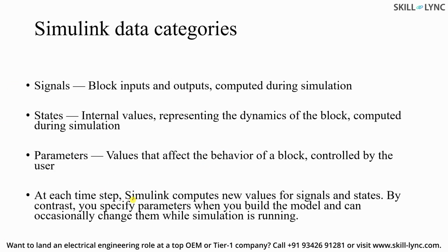Basically, Simulink is going to compute the new values from the signals given as inputs and the present states, and it is going to create all new variables. You specify the parameters when you build the model, and you can occasionally change them while the simulation is running. It's also possible to change your parameters while the simulation is running, which is exactly the same thing we discussed as parameter sweep. So it's possible, but not always, only occasionally.